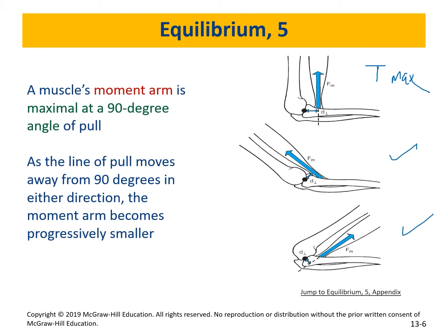Now, what happens is that if you say, well, okay, I'm going to stick with the distance, the one that we started with at the beginning, in order to use it, you need to resolve the force into vertical and horizontal. So this is the force in the vertical direction, and that's the horizontal force. And the force is smaller than the one on the top, even though the distance is the same, which means that the torque is smaller, right? And we're going to look at examples.